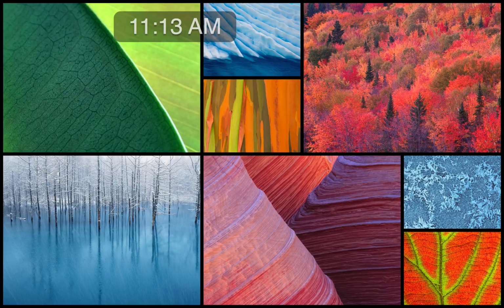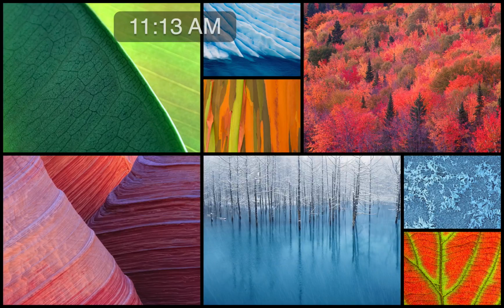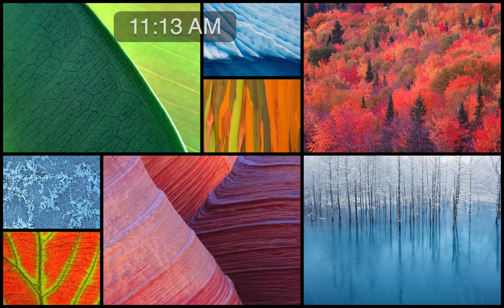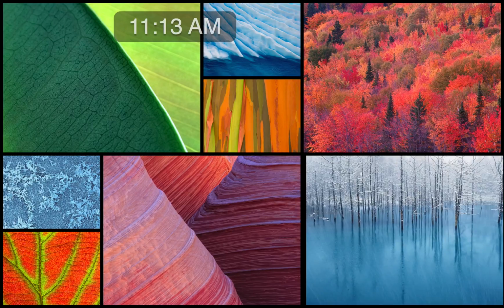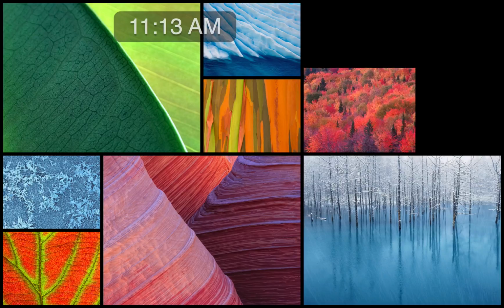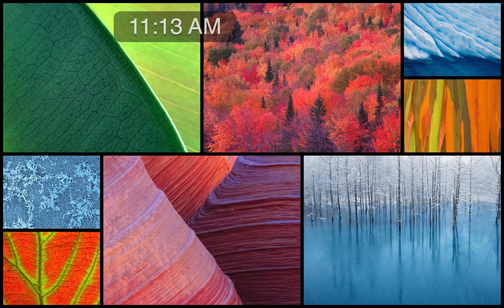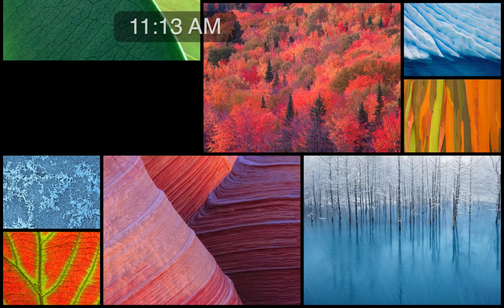Okay, so what I'm going to do now that I have my structure here, I'm going to align my grid line to this, okay? So I'm going to use this edge of the structure to align my grid line. And then now I got to get my 2x4s to fit inside my wall. So I'm going to click this 2x6 and ungroup it from the set. I think that's why it wouldn't let me change it. Change it manually to a 2x4. And then I'm going to align it to this wall. So now it's fitting there.